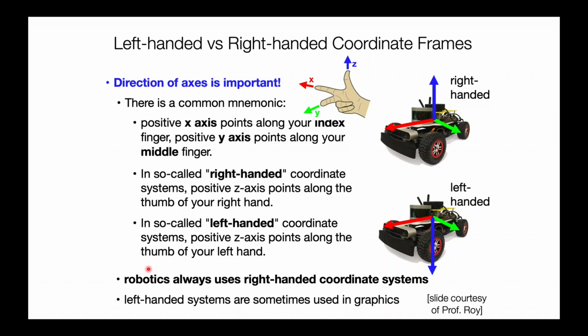So very quickly, let me describe some conventions that ROS in particular uses. In general, you'll find these conventions in a lot of literature in robotics itself. And the key idea here is that the XYZ orthogonal axes follow what is called the right-hand coordinate system, where if you point your index finger, middle finger, and thumb orthogonal to each other using your right hand, then your index points towards the x-axis, the middle finger points towards the y-axis, and the thumb will point towards the z-axis.